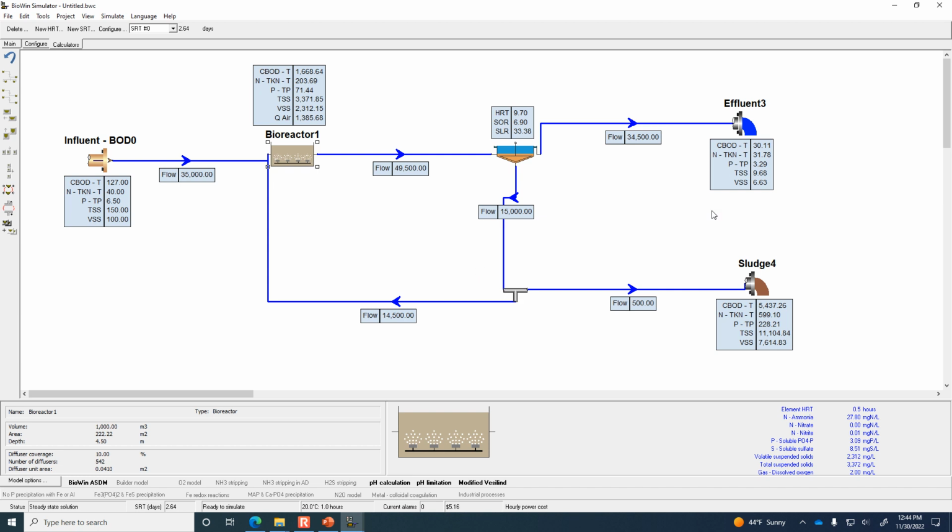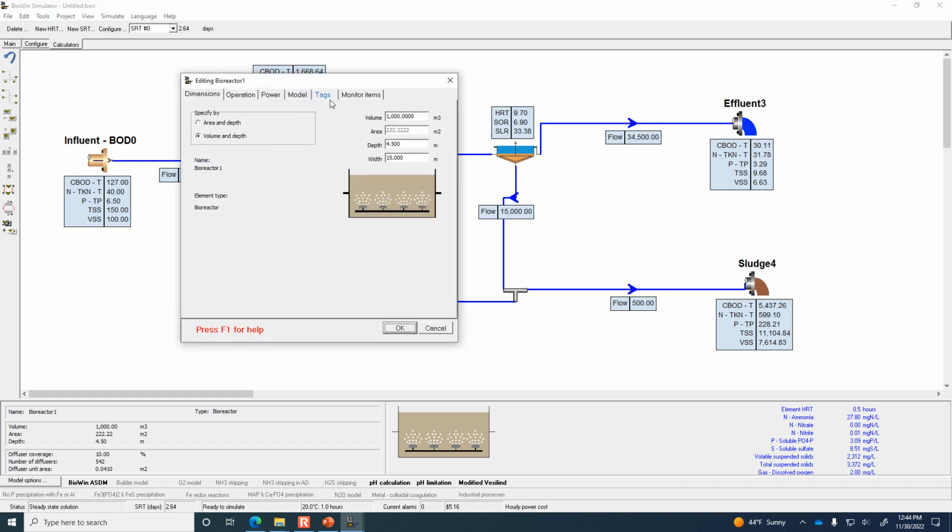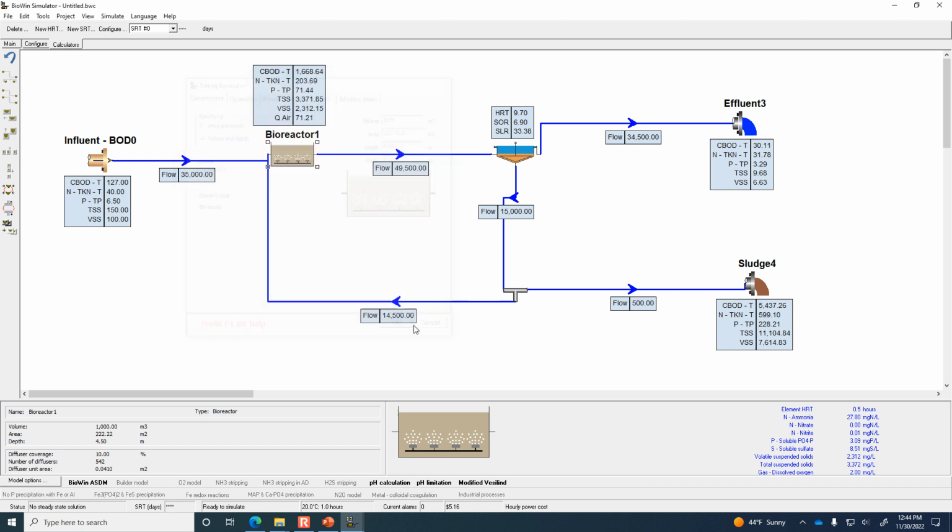Okay. We went too far. Now the BOD is 30 milligrams per liter. So this is the classic engineering technique of iteration and optimization, kind of trying to find that ideal volume, which I think when I did it before was 1616 cubic meters. We run the model there.